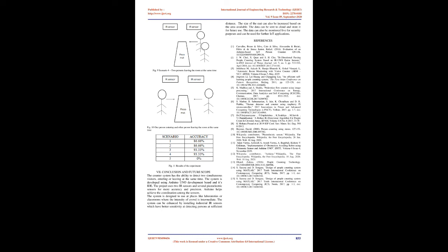For methodology, the system consists of a piezoelectric mat. The piezoelectric sensors are distributed evenly on the mat and the connections are made to the analog pin of the Arduino UNO board. Two IR sensors are installed at either end of the mat at a sufficient height from the ground. The first IR sensor, which is programmed to detect the entry of a person, is placed on the exit side of the mat. The second IR sensor, which is programmed to detect the exit of a person, is placed on the entry side of the mat.